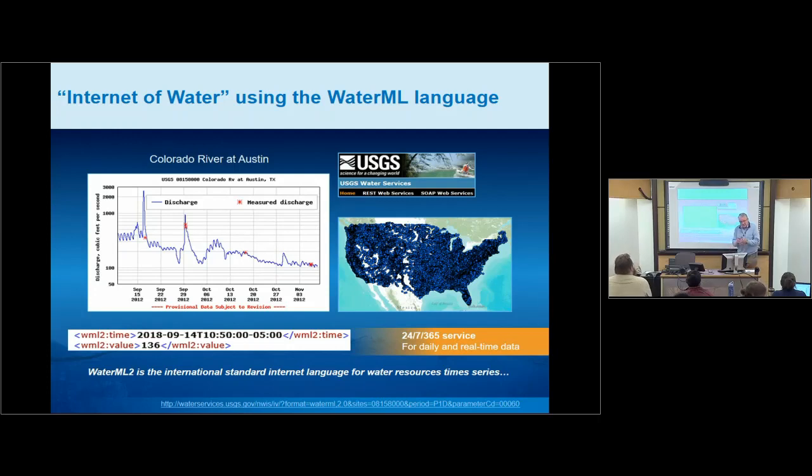So here, 2018-09-14, that means the 14th of September this year. 10:50:00, that means 10:50 in the morning. Minus 5:00, that means 5 hours before Greenwich Mean Time. So that's called Universal Time Coordinated. The discharge was 136 cubic feet per second. So the USGS has mounted this water data services for all their gauges across the whole country, and it runs all the time. So machines don't have to go to web pages to figure things out. Machines just talk to machines and figure things out.